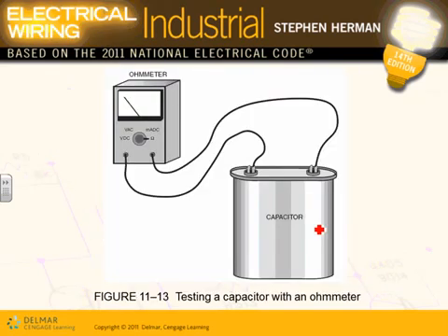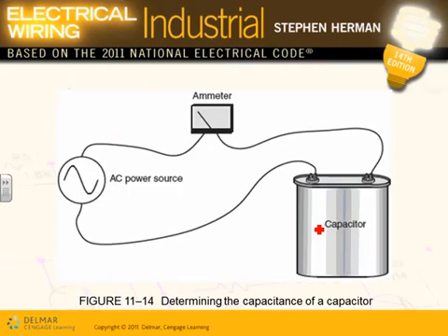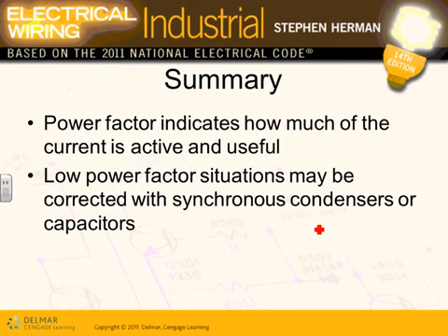Anyway, you guys are designers, so you don't have to worry too much about that. But be aware that your capacitors have to be tested. If they're not working, this means they're either short circuit or open. So you have to provide capacitor testers. Typically multimeters, Adam, will test the capacitors, the insulation of the capacitors. Different ways of testing. So that's basically what the power factor, guys, is.